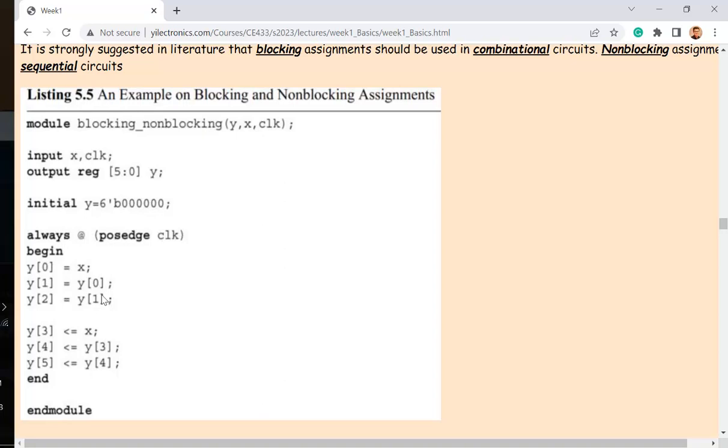That's why in Verilog, you can see this is how we put a clock in the circuit. So always at a rising edge of the clock, then do this. If you have only one liner there, you don't need a begin and end. If you have multiple lines, you have to use a begin and end to wrap it up, right? So it's being included in the one always block.